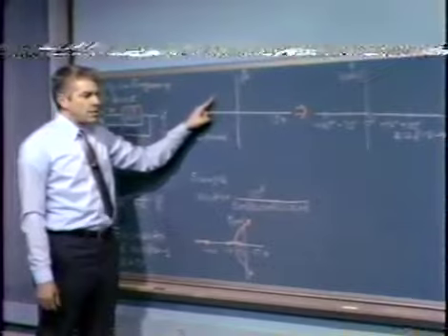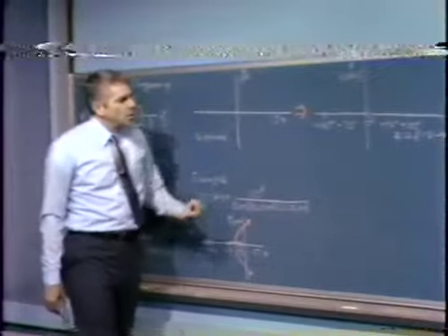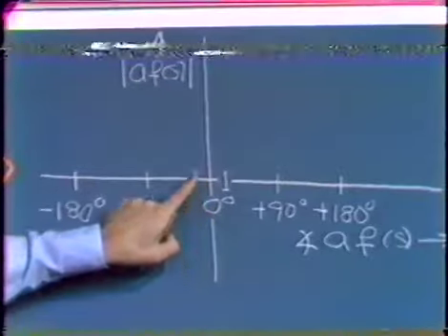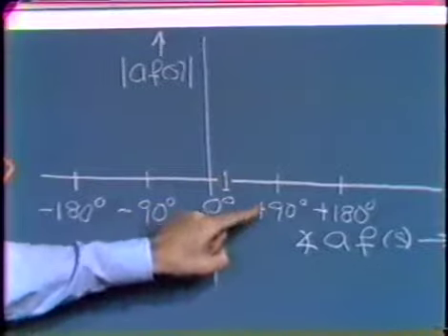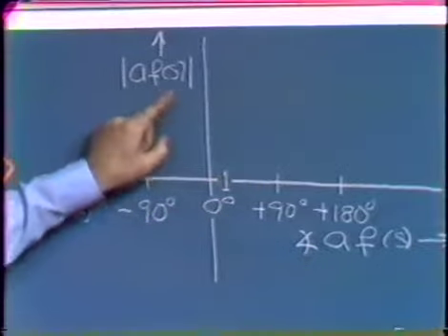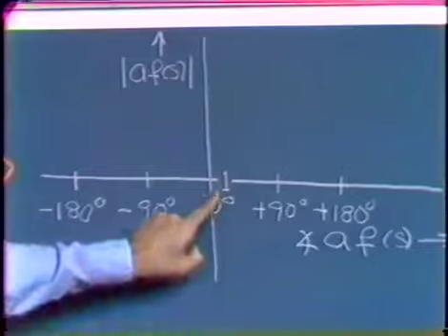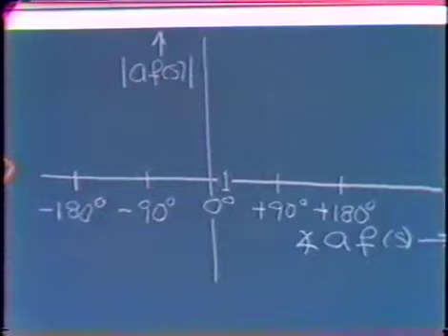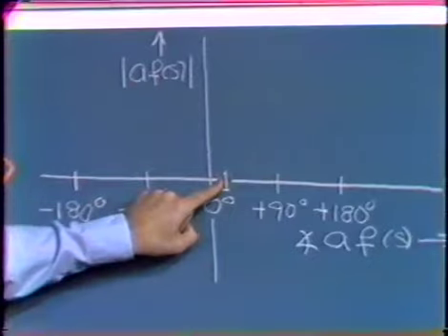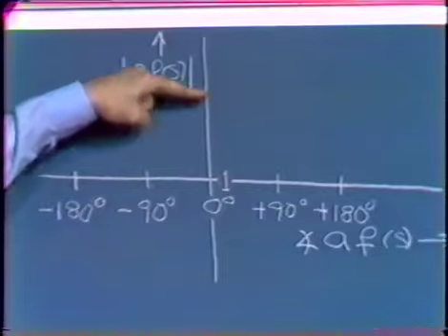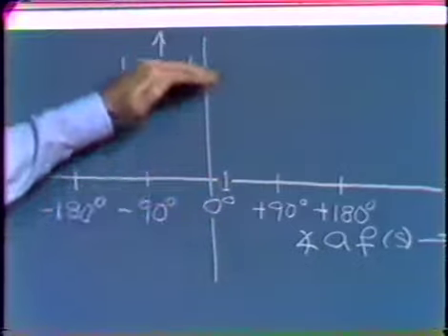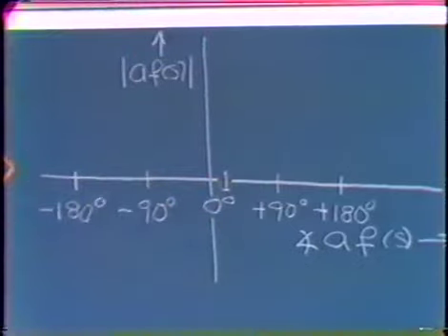And we choose to write that AF product in a particular form. We choose to use a so-called gain phase representation for the AF product. In other words, here we have a gain phase plot in the AF plane, if you will. This axis is magnitude or gain, generally for the same reasons that we do with a Bode plot, why we use a logarithmic presentation. So here we might have unit magnitude, a magnitude of 10, 100, and so forth, a tenth, 1/100th. Again, as I say, a logarithmic scale is usually most convenient because of the large dynamic range associated with the magnitude of the loop transmission.